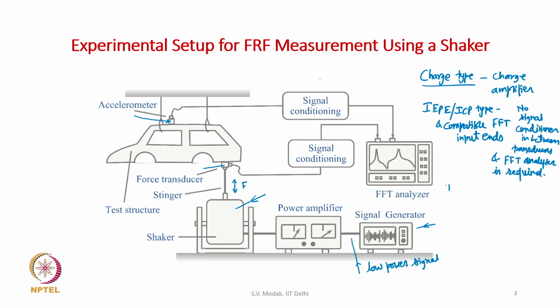So, if we have IEPE or ICP types of transducers and the FFT or DAQ system does not have compatible input ends, then a signal conditioner is required.